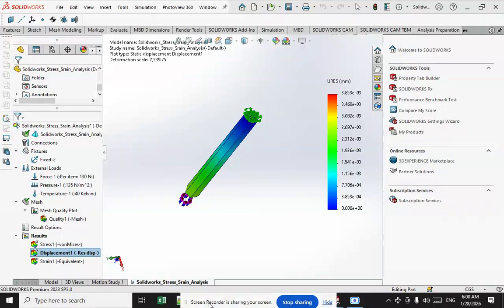One may be able to determine a priori that in some parts of the system the stress will be of a certain type, such as uniaxial tension or compression, simple shear, isotropic compression or tension, torsion, bending, and so on. In those parts, the stress field may then be represented by fewer than six numbers and possibly just one.